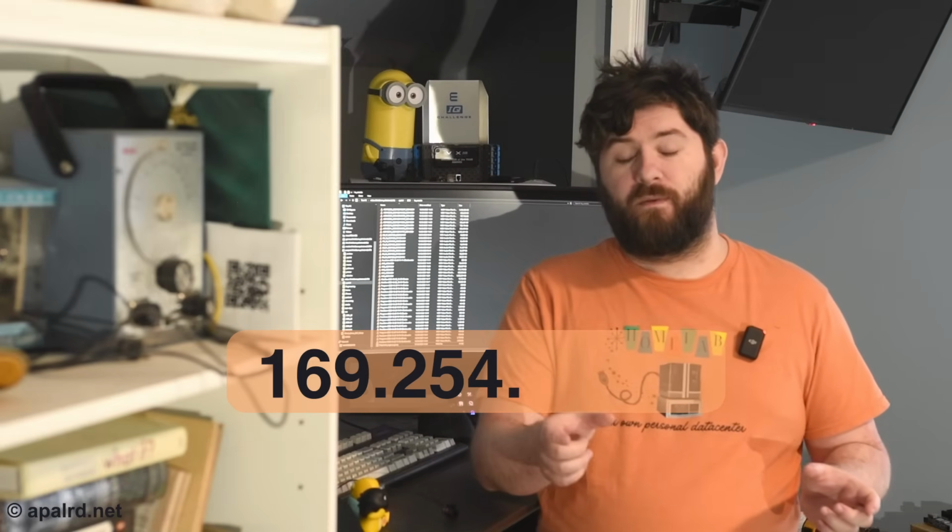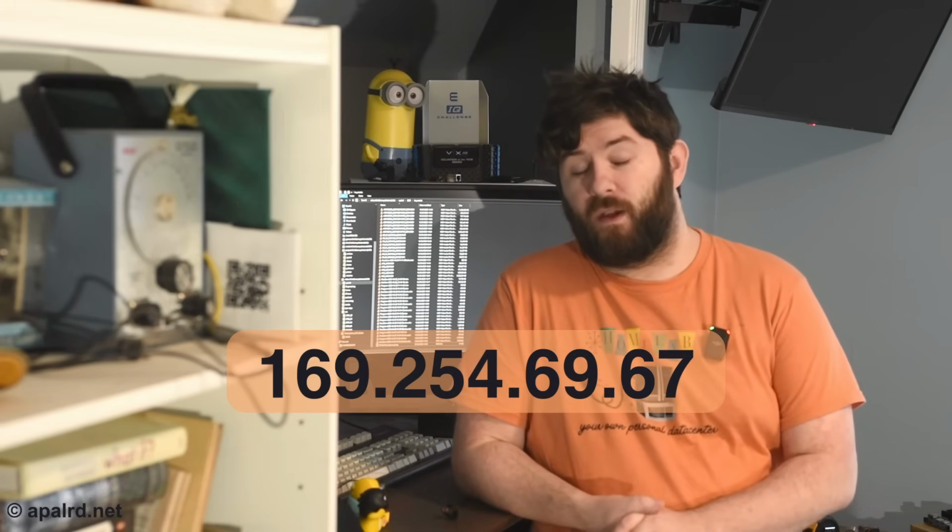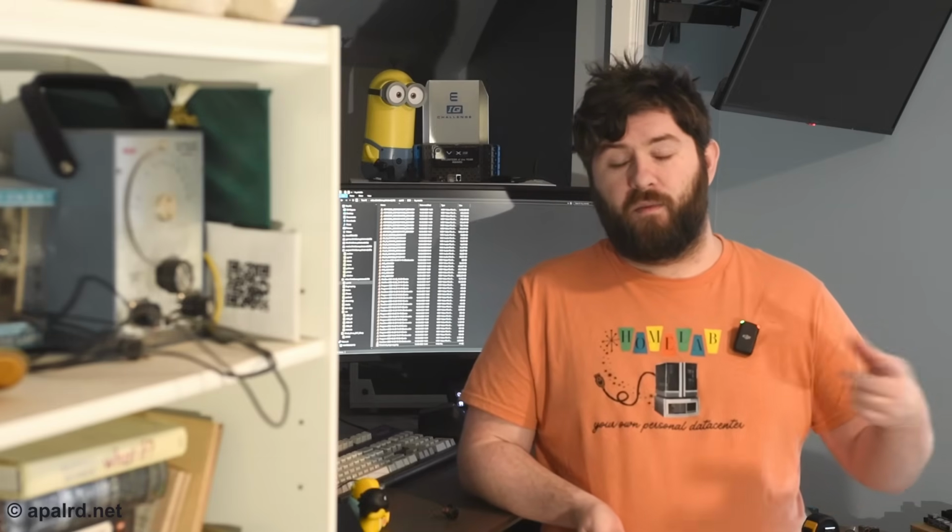And the presence of a global address doesn't deter them from still talking to each other with their link local address. So in IPv4, if you were to do the 169.254 trick, which is valid IPv4 link local addressing, then you can only talk to each other, and if you suddenly get global connectivity from DHCP, then you have to figure out each other's new IP address because you don't have more than one IP address at a time. So that's why I've chosen to use IPv6 for this, to make use of the link local addresses for machine-to-machine communication on the same bus, with the possibility of using global addresses for remote flashing or other optional features that don't directly impact the functionality of this.